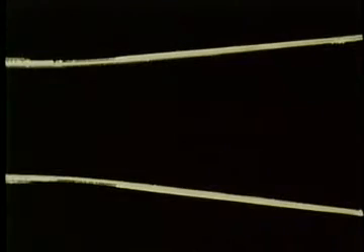In this diffuser, which was used before, we have made the bottom boundary layer turbulent by inserting a trip rod upstream. The turbulent boundary layer is able to withstand the adverse pressure gradient in the diffuser, while the laminar layer along the top wall is separated, allowing reverse flow.